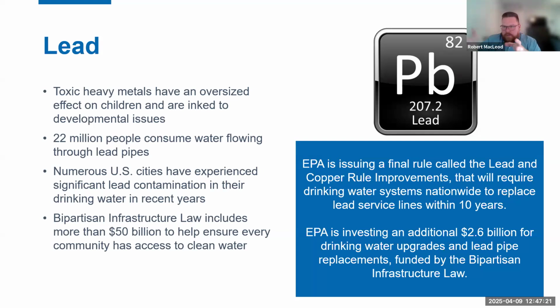So every single potential water source within a school, the boards were sampling, sending off, getting the test results, and having to then do something about it. Whether that be flushing, adding point of use filtration, or repiping, all kinds of different options were available, but this is all within our guidelines as well, both from Health Canada down to the provincial codes.